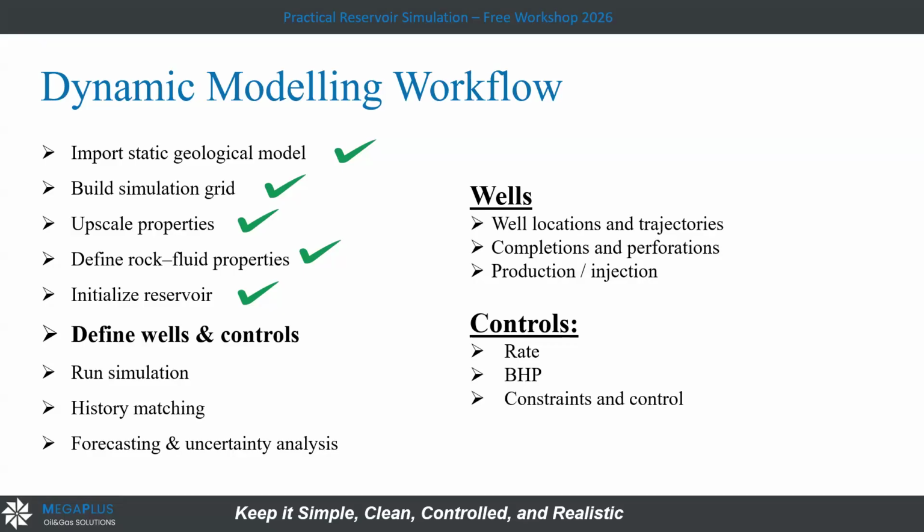You can control the rate. You tell the model, I need a constant rate, a plateau rate, so the model has to simulate the pressure depletion in the reservoir with this rate, or vice versa. I need to control the pressure, as I have an active aquifer for example, and see how the rate will be simulated. So after I make the initialization, I have to define the wells and the control in the wells in the dynamic model.